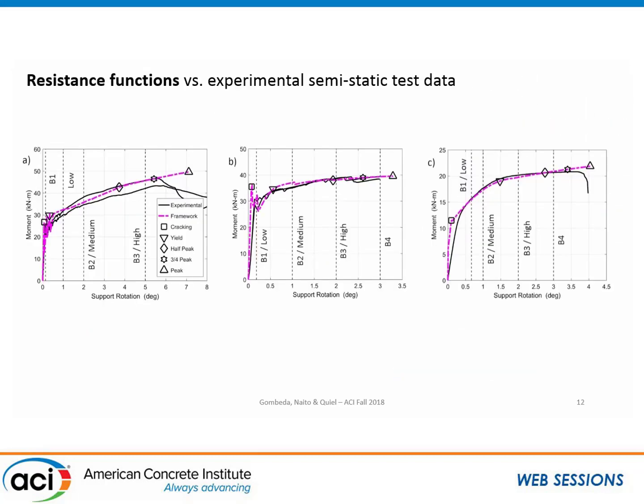And there's the blast load at the end. So crucial to this is looking at the static test as well. We've used comparisons with static test data just to make sure that our approach captures the relevant limit states of the panel. And again, this is baked into the paper, but I just wanted to show this to reassure that we've gone through the steps to evaluate that the model works statically before we jump into a dynamic effort.